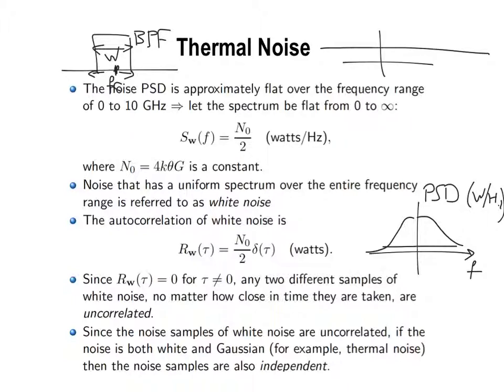So basically, out of all this noise spectrum, you will only be getting this part and this part, the positive and the negative side. So your power is going to be only the ones contained here. So you'll have a limited power. Otherwise, none of our receivers will work. That's why at the input of the receiver, you have to have a band pass filter so that you limit the amount of noise that you are collecting from your electronics, okay?